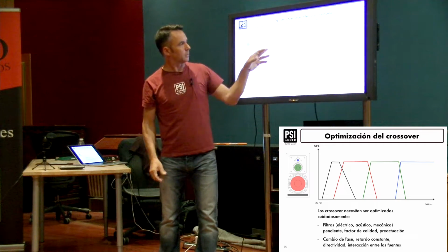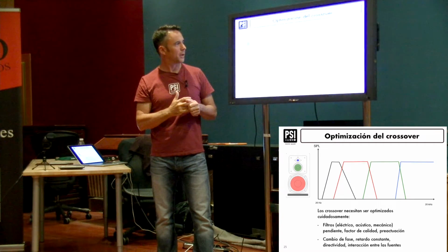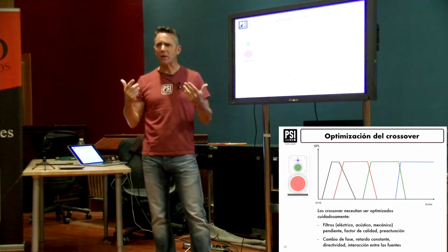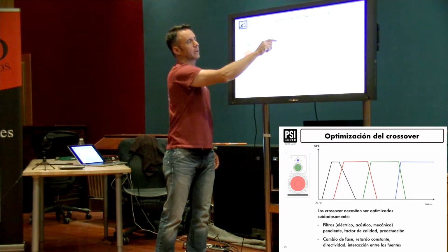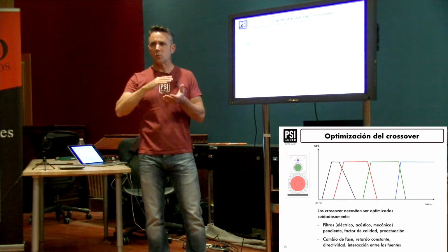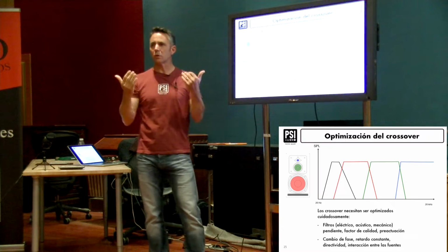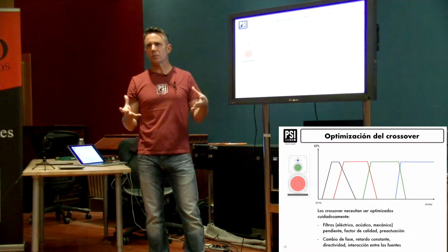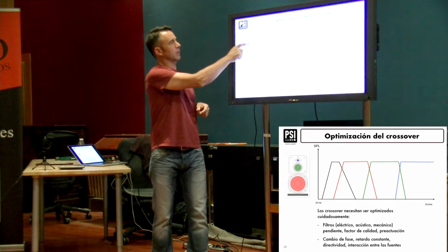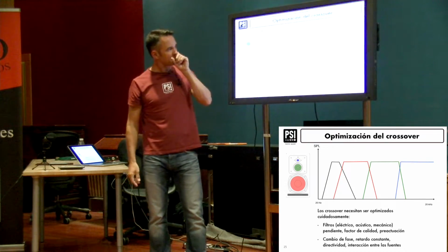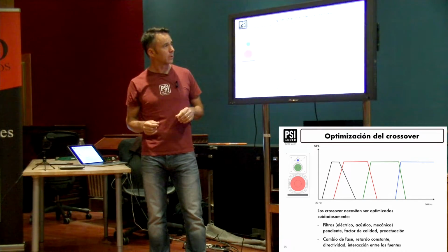You can play with the different slopes. You can play with the Q factor, which means, does it go more round or does it go up a little bit and down? You can play with some pre-accentuations here, so you can make it go up and down. There are lots of things you can play with, and it all depends, but it has to be adjusted to what the driver can deliver, what can come out of here and here, so that you adjust it all nicely, taking into account all of the characteristics.